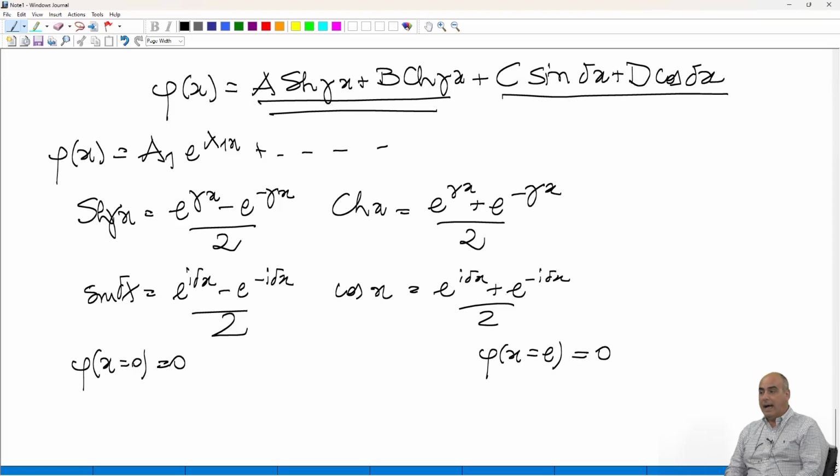We need to find the other 2 boundary conditions. We do only know that our beam at the edges is torsionally supported by a fork. The fork prevents the rotation, phi equal to 0, but leaves the warping free.